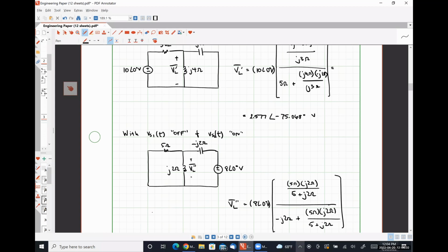Here we're combining these two impedances together, and it gets really small when we combine them together, which is why we see that the voltage gets attenuated. Here, when we combine those impedances together, its magnitude is actually larger than either of the constituent parts, which is why our voltage drop gets larger. And it is absolutely due in some part to the frequency dependence of the impedance of the inductor and capacitor.